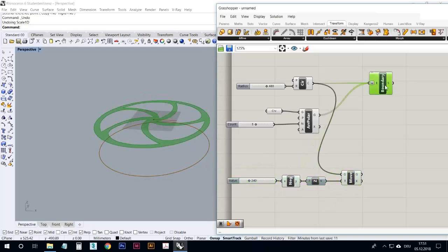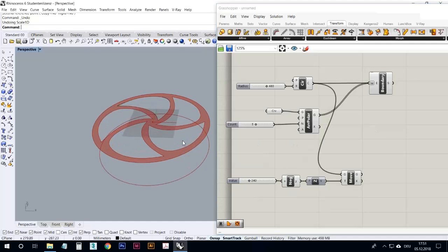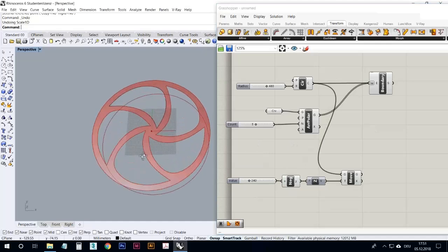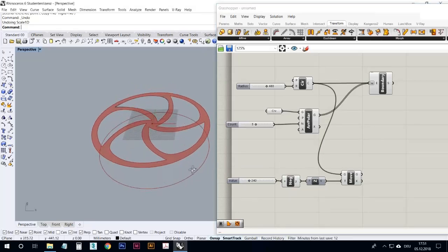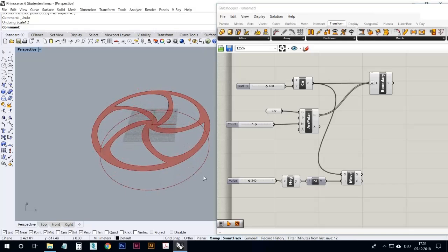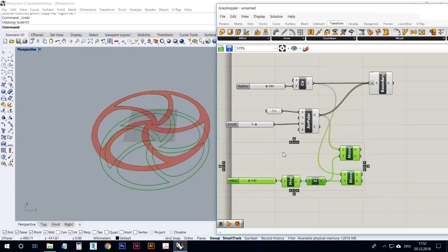So now you wonder why I didn't move this, right? But it's because we're gonna scale these a little bit, the holes, so that we got another appearance, which is not. Otherwise, we could have just extruded this downwards. So I want to show how to combine surfaces, and then if I extrude, it's already a solid geometry. This is more complex, has much more facets to it. So we have to move these as well. We can simply copy that one, and we have the same movement factor to it.